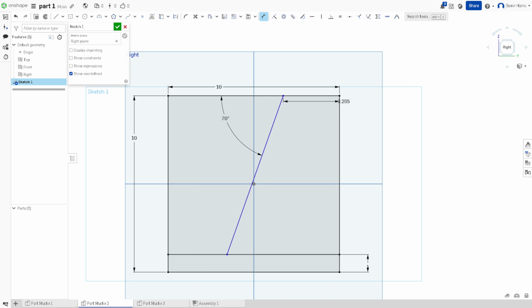So we can connect the top dot and the dot of this line that we created, and say the length is gonna be 1 centimeter. See how also the bottom part moved, it didn't stay in the previous point. And that is why, because first we added this angle that we wanted. So okay, we have our design, but I think the angle is a little bit too coarse, so we're gonna lower it to maybe 60 degrees. See how it moves. Here is fixed because we fixed it with our dimensioning.